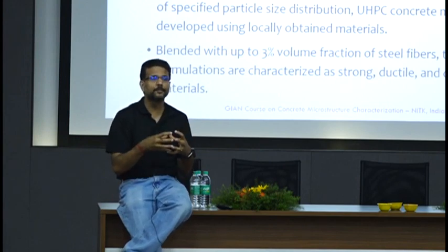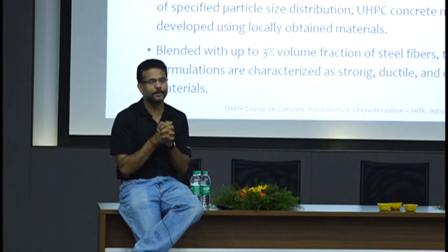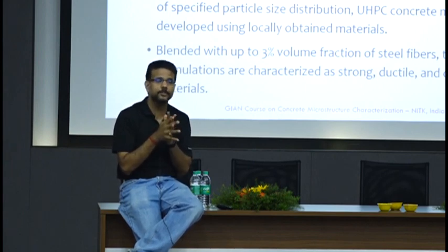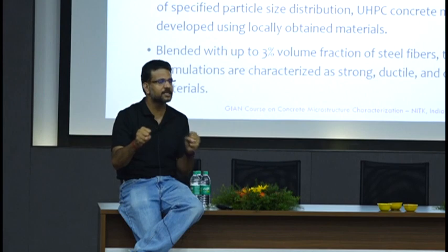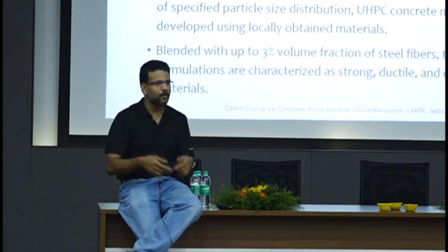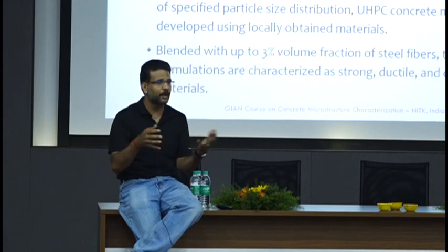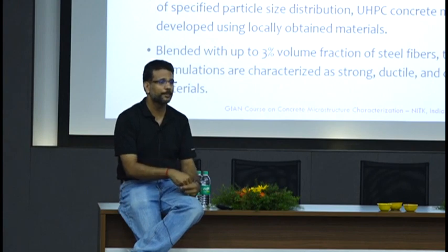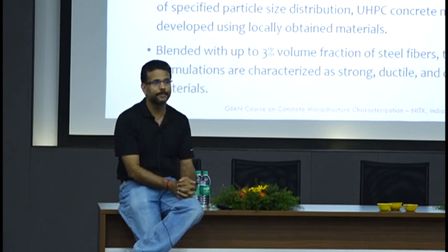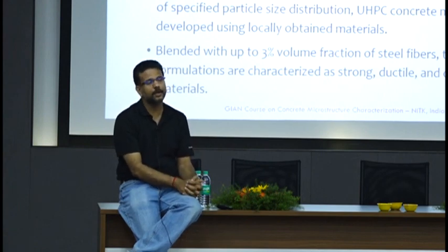Because the effect of superplasticizers, even the latest polycarboxylate based superplasticizers, which are supposed to be very quick in dispersing, when you have low amount of water, you basically have to stretch them out by mixing more and more and getting water away from the particles. You get the steric hindrance away, you get the agglomerations away, so you have to get all of that, and that's why it takes long. But good mixing is a key. And that's where a lot of energy is spent on good mixing, and that's where the cost is increased.